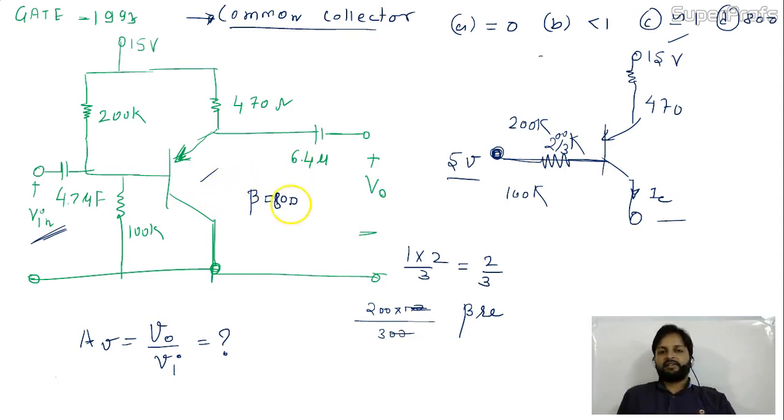We have seen just now that in the equivalent circuit of the BJT, we need beta RE, that is R pi. Beta is available with us. RE we calculate by VT by ICDC. I need ICDC, meaning the collector current IC in DC operation, right? It is fine. Now, where is the VBE? B to E. Here is the VBE. This is the VBE given over here. You need to calculate this IC.